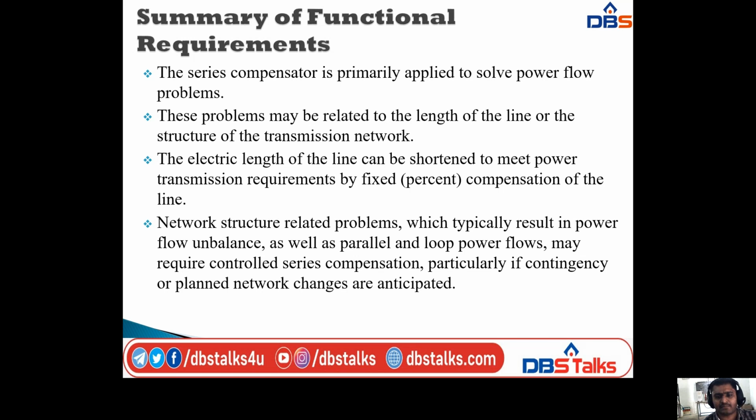Network structure related problems typically result in power flow unbalance, as well as parallel and loop power flows. These may require controlled series compensation, particularly if contingency or planned network changes are anticipated. So at that time we have to introduce this controlled series compensation for the transmission network structure.